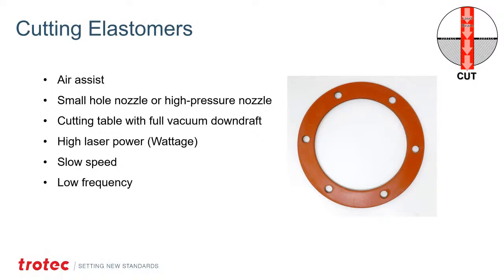High laser power wattage is necessary in order to cut. Productivity is going to be associated with laser power. The more you have, the faster you're going to be able to cut. And in some cases, you won't be able to cut at all on thicker rubbers, or even thin rubbers, with certain wattages. So I would suggest running a test, contacting us. There are so many different densities and types out there that I can't just say, this wattage works with this thickness. I do suggest running tests if you're not sure.